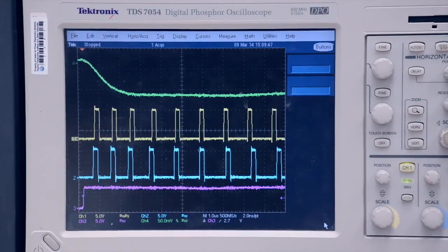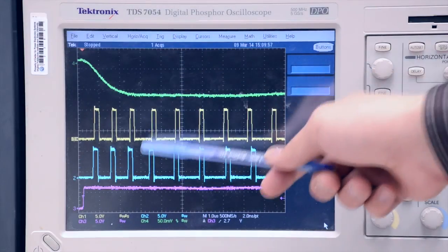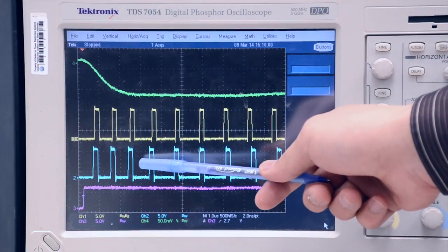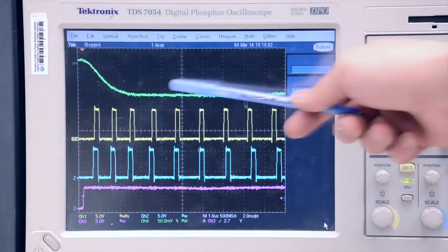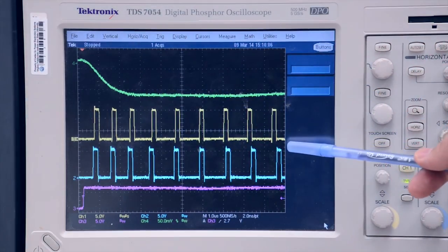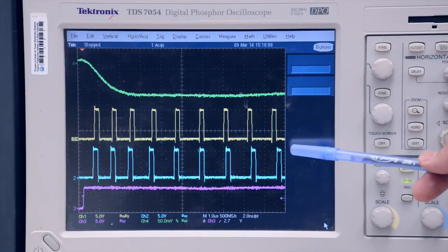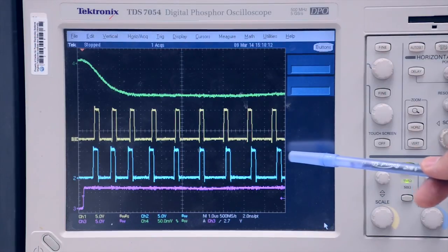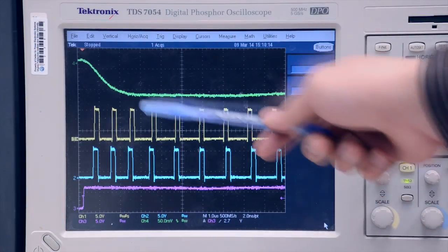Let's take a look at the transient performance. I pick up 2 PWM signals as an example to show the overlapping feature. When the transient occurs, you can see D1 and D3 are overlapped immediately. And then when the transient is settled, D1 and D3 go back to 90-degree phase shift. The overlapping feature allows the inductor current to provide energy to the load immediately, so you can see no undershoot on output voltage.